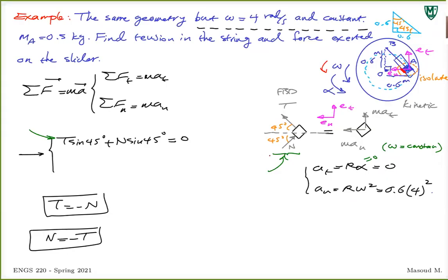Or we can flip the direction right now and get a positive value for n, and solve the rest of the problem. Just going to pause a second to make sure that it made sense. When you assume a direction, like in a free body diagram, similar to what we had in statics, if you're wrong about your direction, you're going to end up getting a negative value for something that shouldn't be negative. In this case, either n is negative or t is negative. So if you get the negative value for n, it means the direction you assumed was wrong. The magnitude is correct.